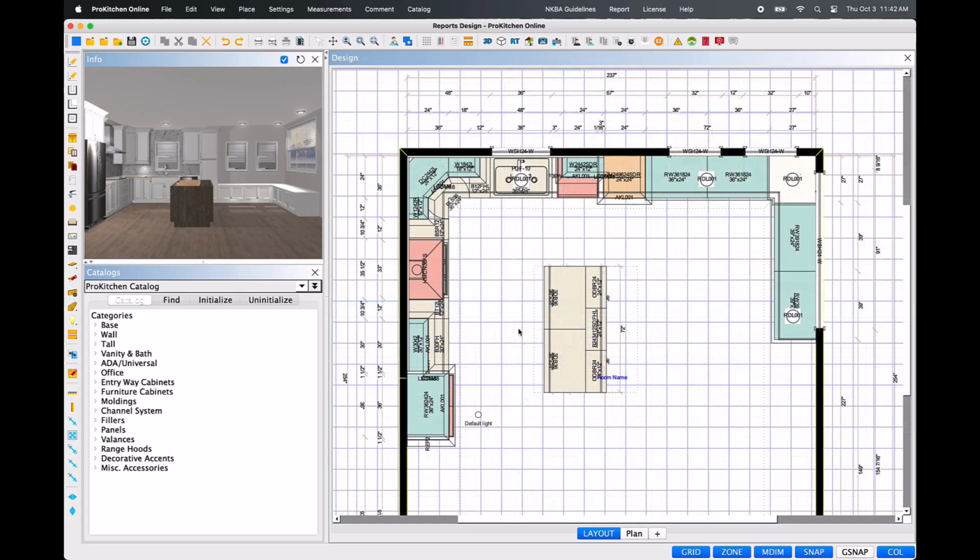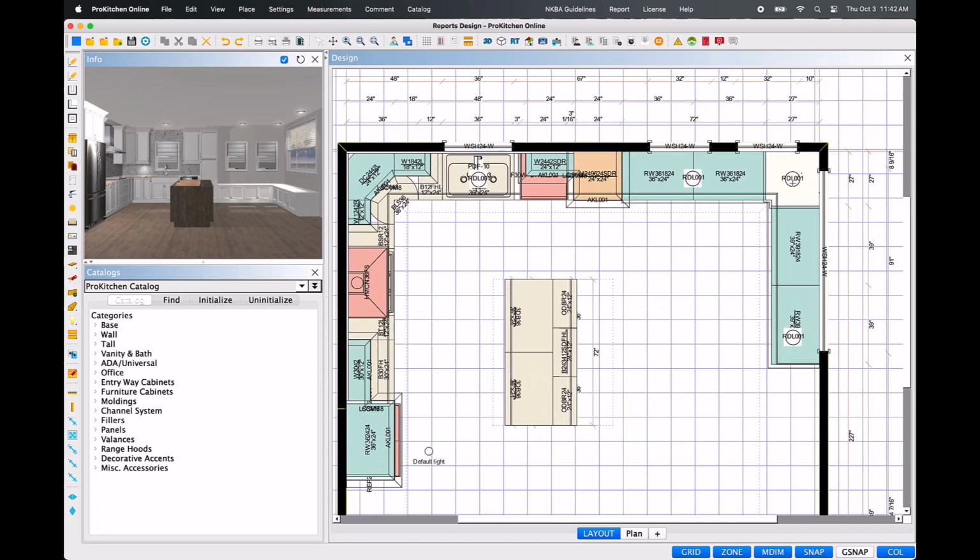The first of the dynamic dimension tools is point-to-point, used for creating a precise measurement between 2 points, or moving one item in relation to another based upon corner or center points. The center points of these two light fixtures need to sit exactly 52.5 inches apart. Moving them manually will leave room for error, so we will use the point-to-point tool to relocate one of the items. Left-click the point-to-point icon, bring the mouse into the plan view, and hover over the stationary light fixture.